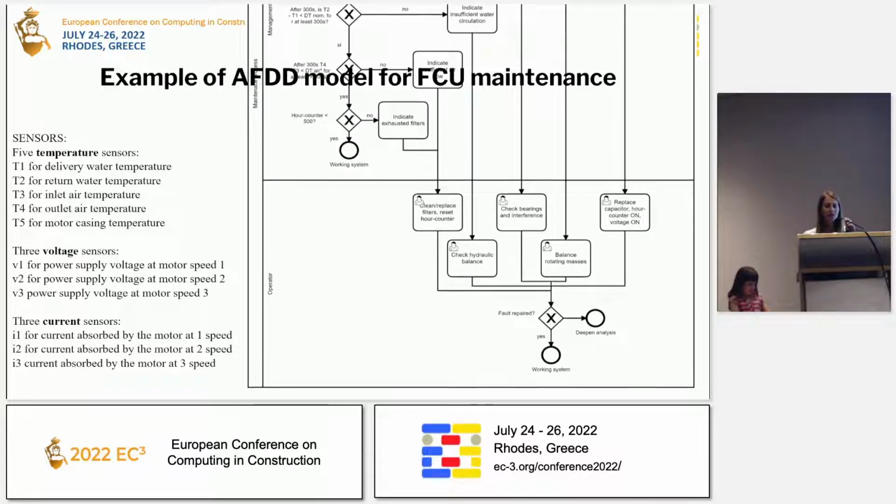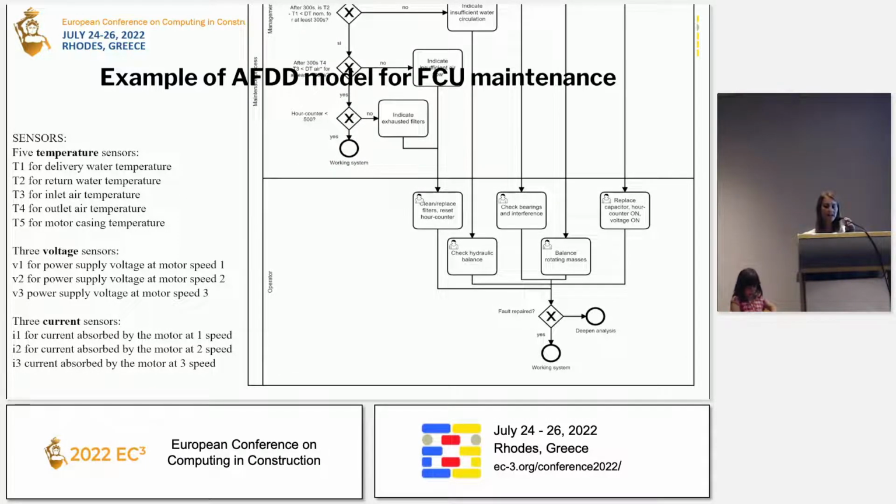The faults which can occur in the fan coil system are insufficient airflow, motor bearing wear, capacitor failure, and insufficient water flow. For each of these faults, a corresponding action has to be taken: clean filter and battery, change bearings, replace capacitor, and clean filter and battery and check valve adjustment, for example. So the maintenance process could be controlled in real time, and when a fault occurs, the system informs the operator or other technician who is responsible for the maintenance.